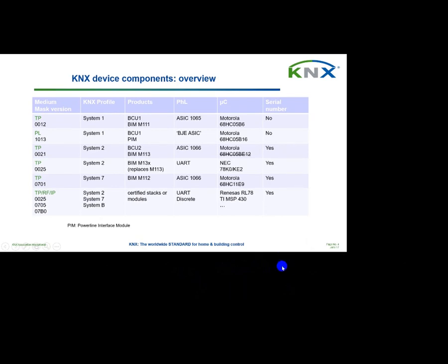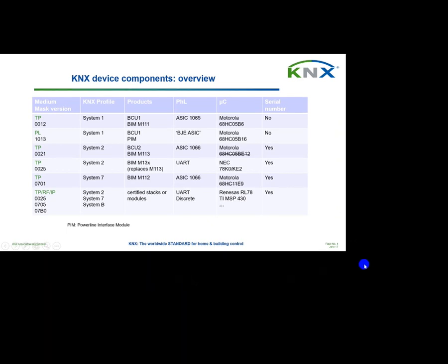The physical layer is either based on a UART or discrete components. And examples of microcontrollers, because this is also open, so it depends a little bit on the provider, are for example the RL78 from Renesas or the Texas Instruments MSP430. Also here serial numbers are supported.